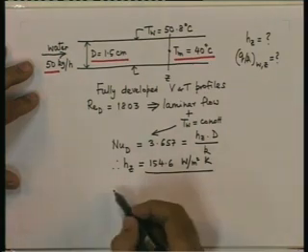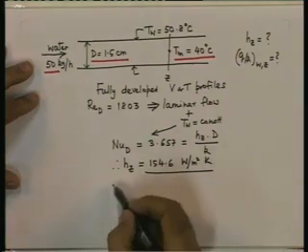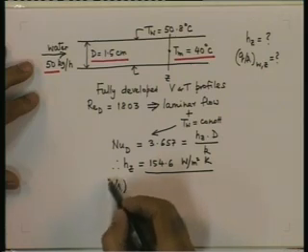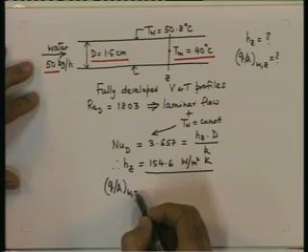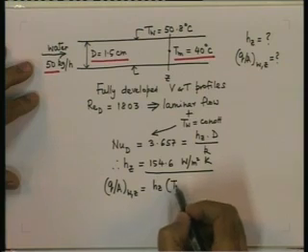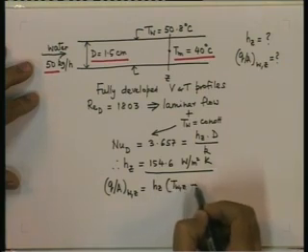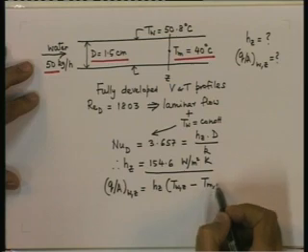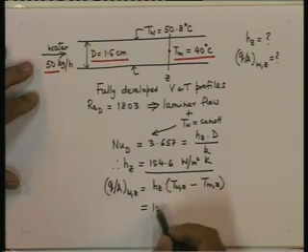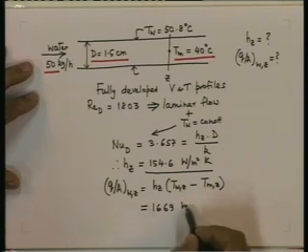And the heat flux at the wall at that Z is calculated as the heat transfer coefficient times the wall temperature at that location minus the mean temperature of the fluid at that location, and this turns out to be 1669 watt per square meter.